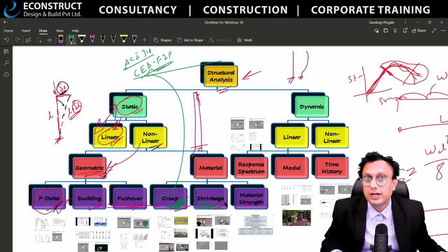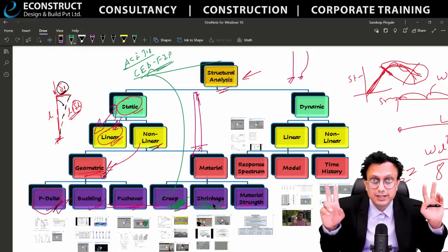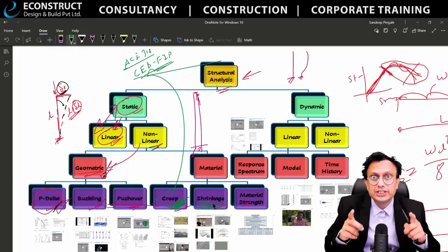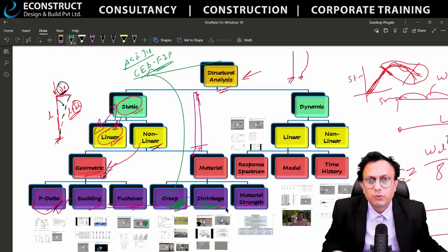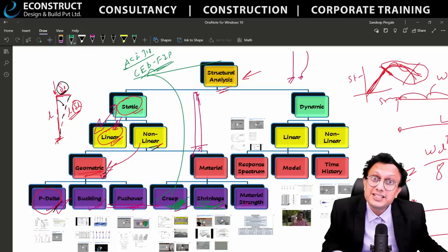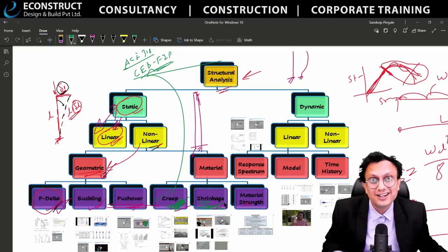Right? Don't panic with this. There are so many options where you can get rid of this shrinkage. But is it really good for the structure? Answer is big no. It will crack. Any non-engineered crack is a failure. Come on, say with me. Any non-engineered crack is a failure, right? What is the engineered crack then? Expansion joint, construction joint is an engineered crack.